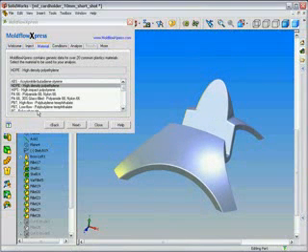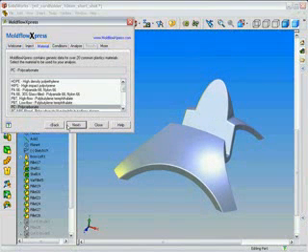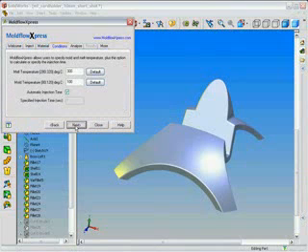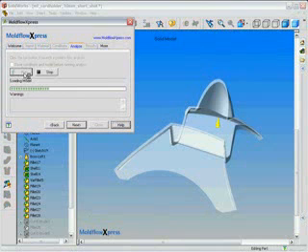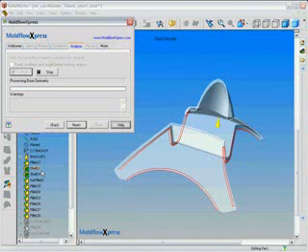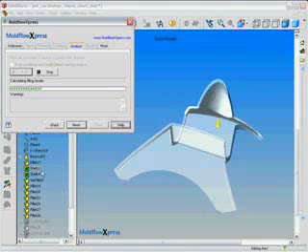From a list of over 20 materials, users are given particular material properties important for the injection molding process. Users then can specify process conditions or accept default values and go ahead and run the analysis. Based on the given boundary conditions, MoldFlowXpress will interrogate the model geometry, and determine, based on the material, the mold temperature, and the melt temperature, whether this part can be made in an injection molding process.